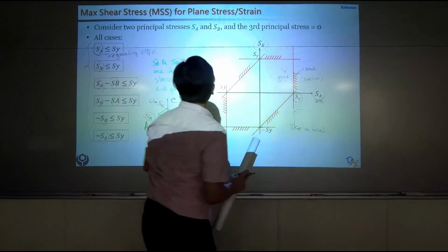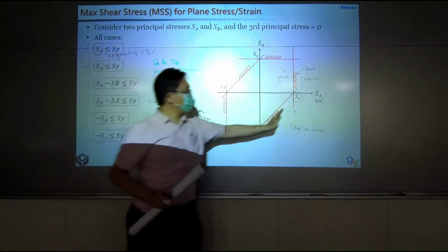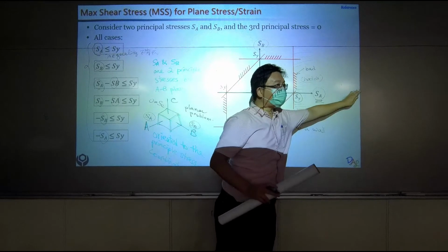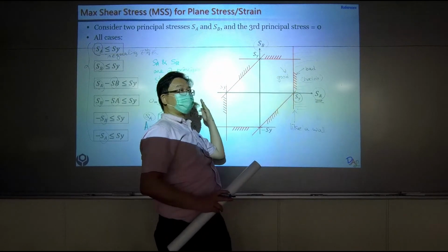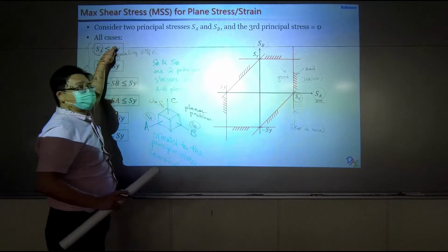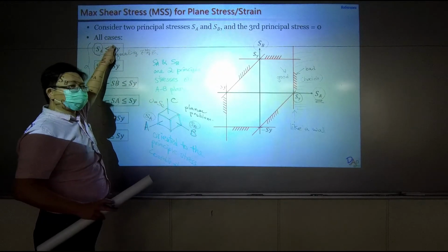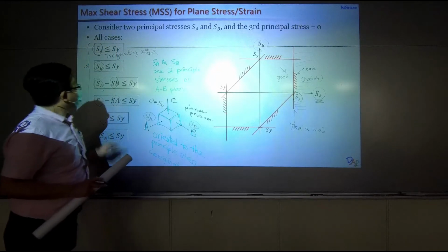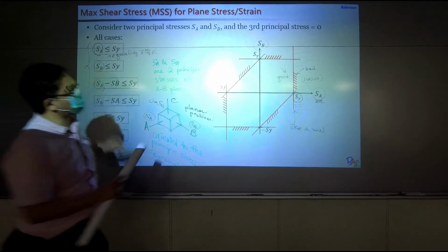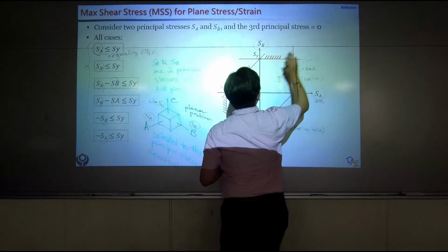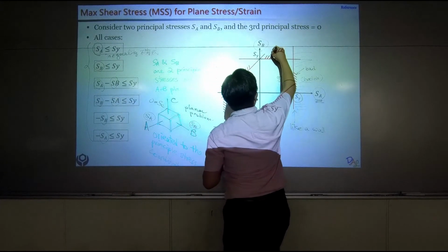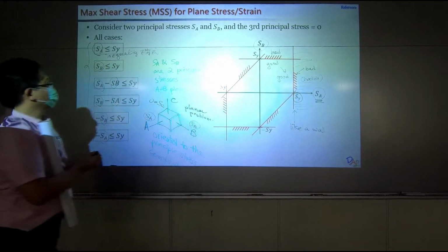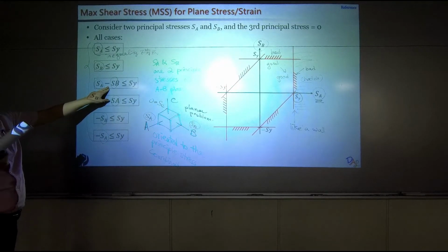And this equation basically is this boundary. Over here is bad, over here is good. Because if you follow, it will be safe. If you don't follow, it will yield. So let's follow this. Now the second one is SB smaller than SY. That would be this equation on the top. This side is bad. The bottom side is good. The third equation is a linear equation.